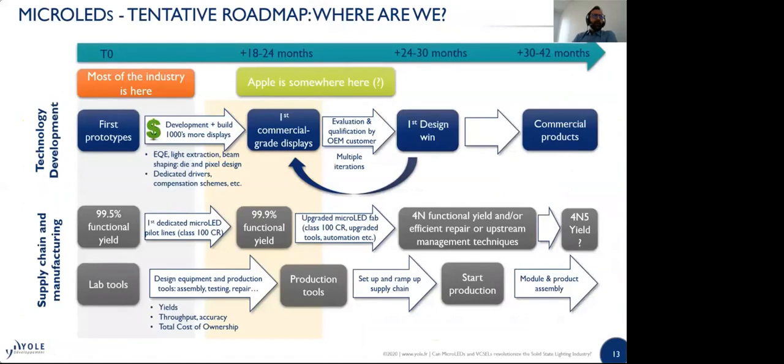So for micro-LEDs, we have taken a look at the past; what is likely to happen now in the future? Here you have a tentative roadmap in order to understand where we stand and where we are going. Epitaxy and chip fabrication are no longer seen as roadblocks, but solid yield management and repair strategies must be implemented. Transfer and assembly processes need to evolve from tabletop experiments to robust high-volume production tools. The proliferation of technology paths indeed creates some confusion and delays.